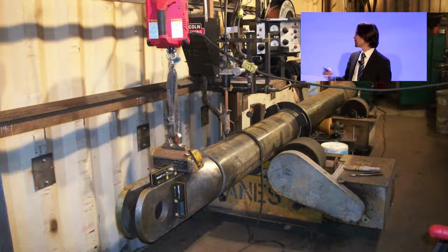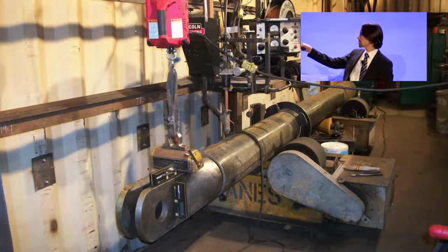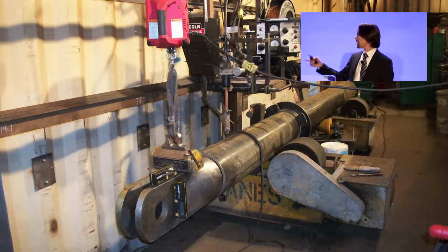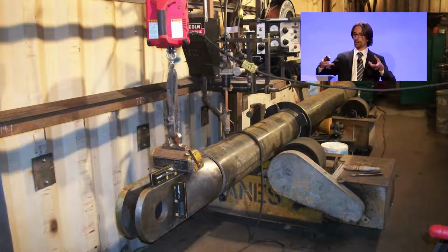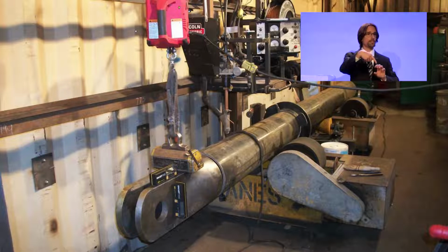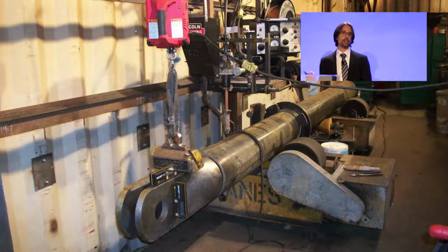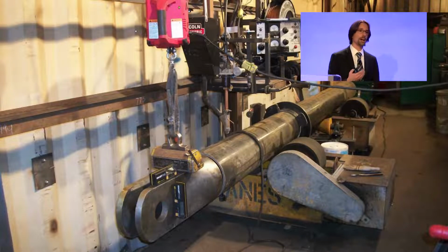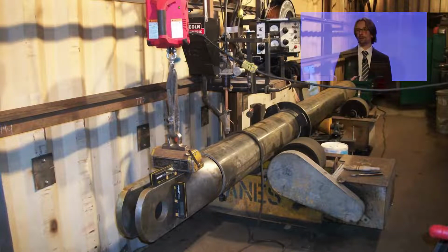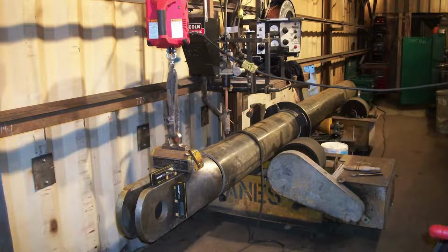So here, for example, you can see one of the pin connectors that's going to be welded onto the end of, say, a column or a brace. And that fabricator has mounted that member on a turning spindle, and that groove weld between the casting and the pipe is just going to be simply filled up with this automated welding machine. So it's very rapid fabrication of architecturally exposed structural steel that's very high quality and very low cost because they're standardized fittings.